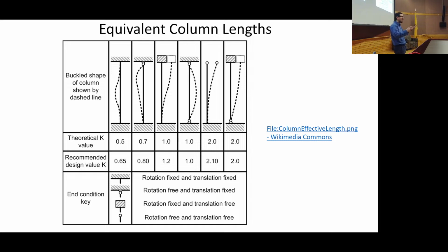Yeah, I like the facial expression with that too, Bobby. Okay, so that was good. That's right. So like you're pushing it together in one direction, but it flows out in an orthogonal direction. And when it comes to Euler, this is what we call elastic instability. So the buckling is not dependent on the yield strength of the material if it has a very high slenderness ratio.